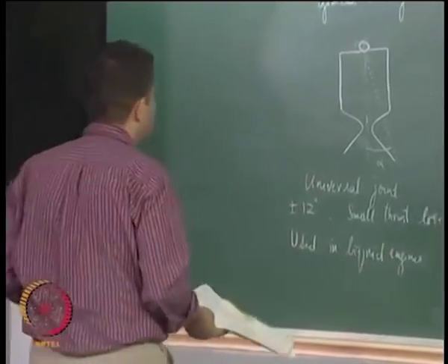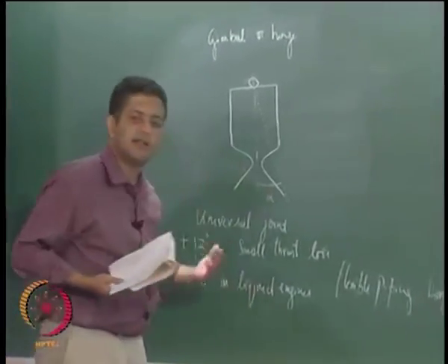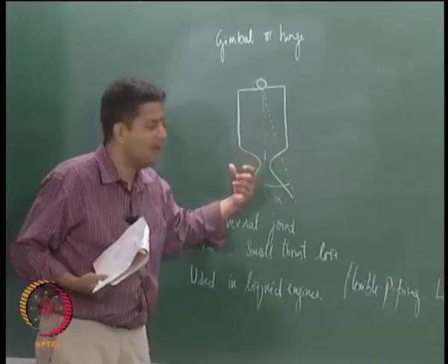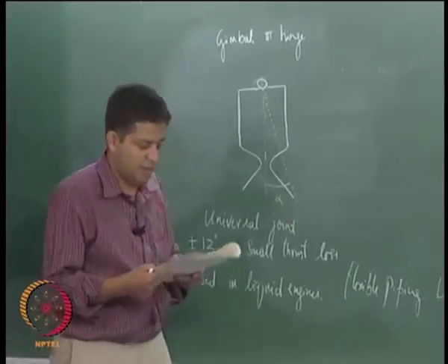Instead of gimballing the entire engine, the other option is, can we just move the nozzle itself, and that is called a flexible nozzle.